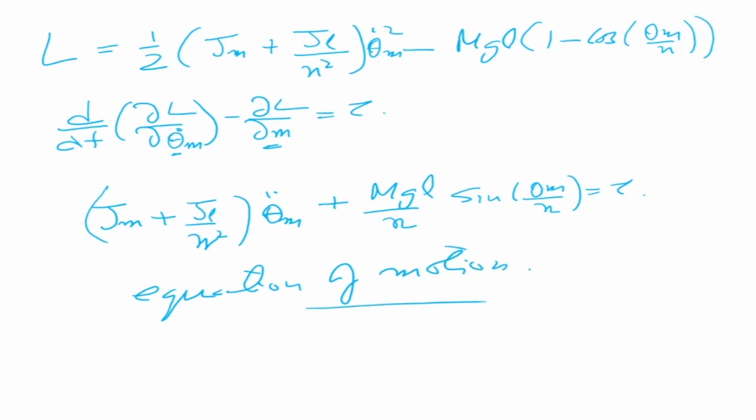Okay, so what we have done is we have found the equation of motion of a one link system using Lagrangian-Euler dynamics. Now this is only one link. So there you have inertia forces, which is this one, so you can see it is mass. Inertia is equivalent to mass into acceleration. So mass into acceleration is here. This is the inertia force, so this is my inertia term. Then this fellow is my gravity term. So mg is there, so mgl is the gravity term. There is no centripetal or Coriolis force because there is only one link here. So no Coriolis and centrifugal.